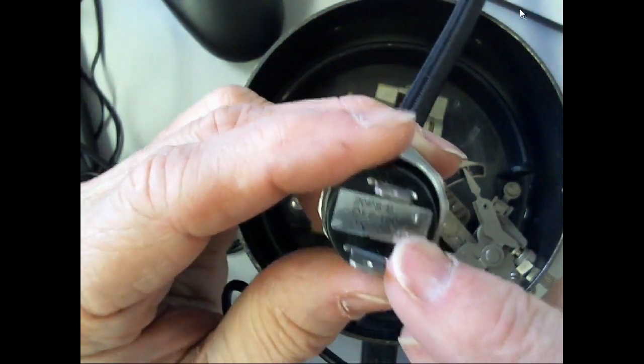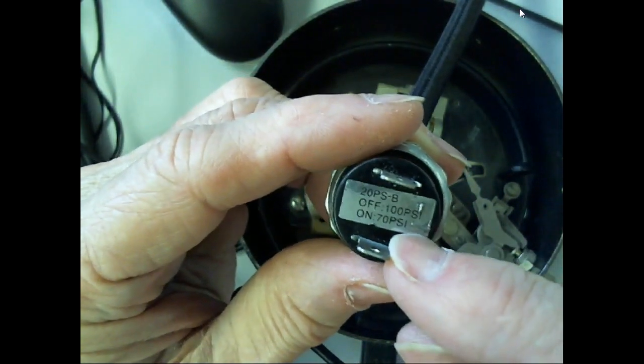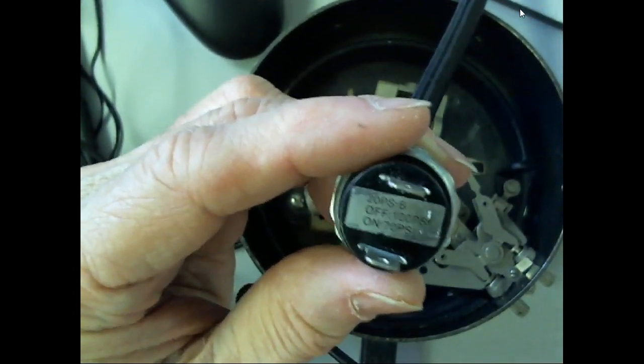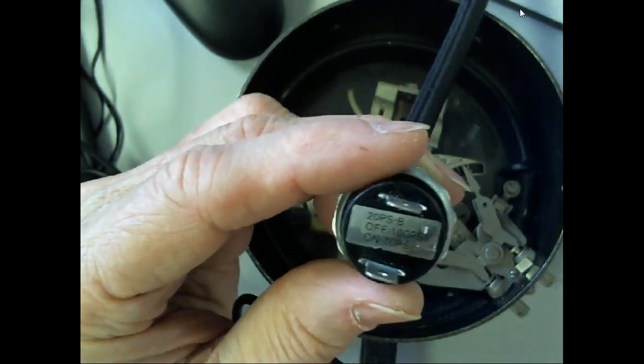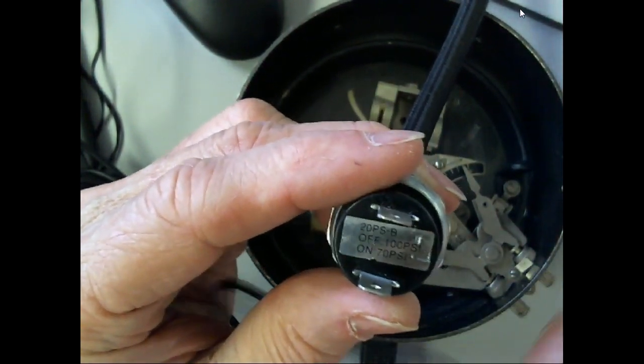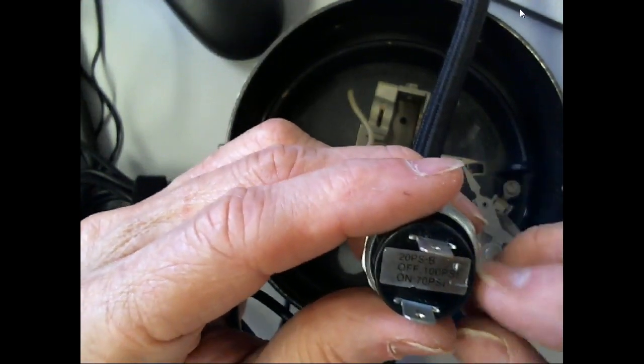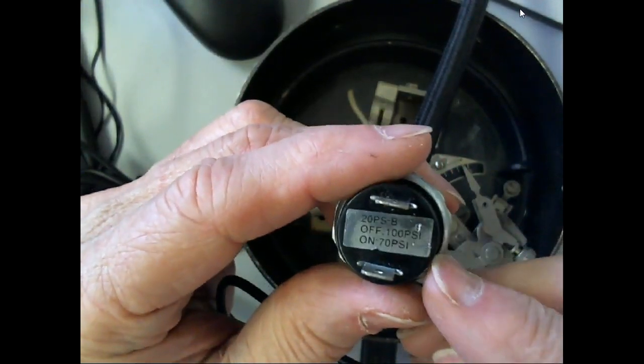So your tools are run at what? If you ever look at your standard tools, they run at 60 psi. You're supposed to run at 60 psi. A lot of people run them with more. Yeah, but you're going to cause them to go bad faster, right? Because of the seals and everything.